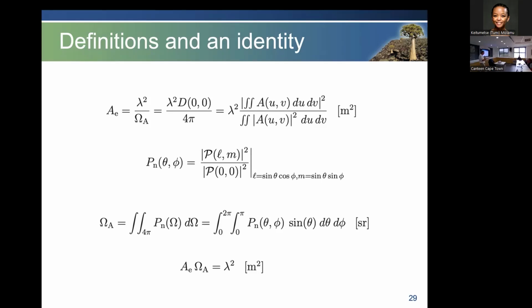In fact, it's kind of hard to get it up to 90% efficient. But if you go to clever people at Stellenbosch University, they will find ways of shaping your dish and optics so that you can get up towards 90% and above. So the effective aperture is, how big does this thing actually look? If you think of the antenna as a rain collector, how much rain am I going to collect on this aperture if I measure how much water I've got out?